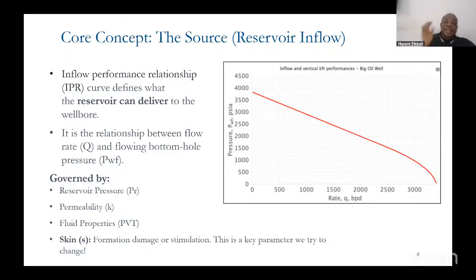So those are things that also contribute to skin. Then the chief of them is formation damage. Fines migrate as you are producing and plug the pore spaces and their interconnectivities, thereby reducing the permeability near the wellbore. So you may need to stimulate it.